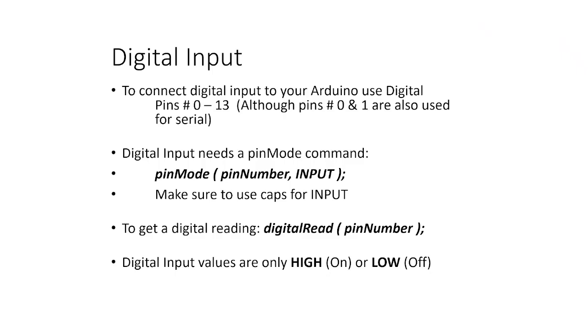Digital input: to connect digital input to your Arduino, use digital pins 0 to 13. Although, as I told you, pins 0 and 1 are also used for serial communication. So if you have connected anything to pins 0 and 1, you always need to disconnect them before uploading any code.